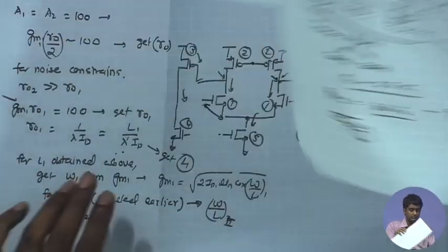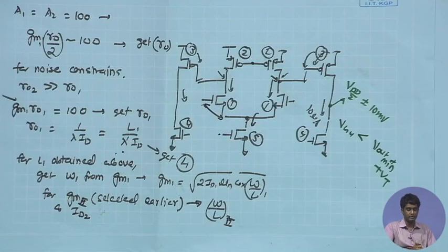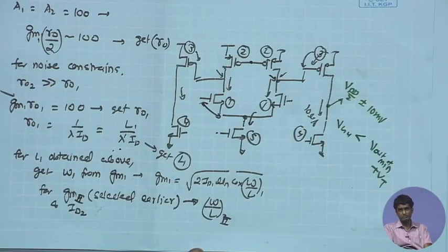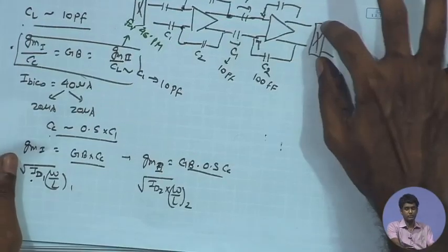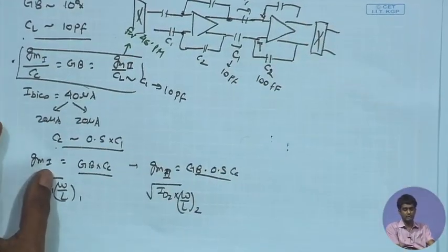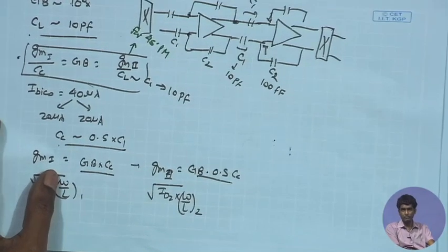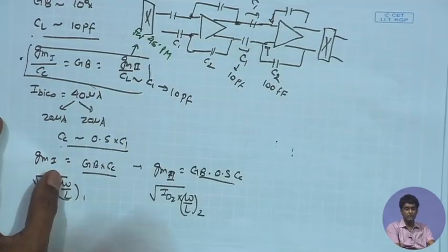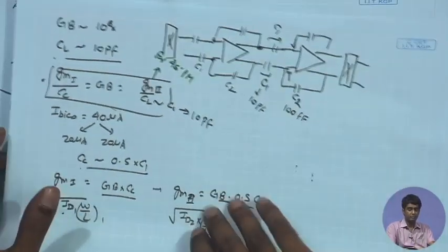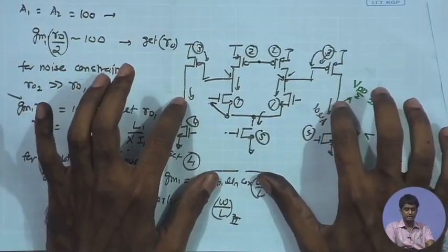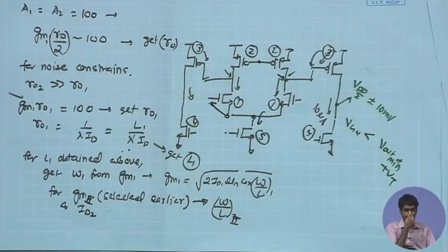Now, we know that for the second stage amplifier, one of the very important constraints will be the output swing, because if we look at the numbers that we are using, input signal say 100 microvolt, the overall closed loop gain of the first stage 100, second stage 100, 10 to the power of 4 overall. So, the signal over here that we are getting can have an overall signal swing of 1 volt peak to peak, right, 100 micro times 10 to the power of 4. So, I can expect even up to 1 volt peak to peak signal worst case, and I have to make my output stage such that it is capable of handling such a large signal swing.